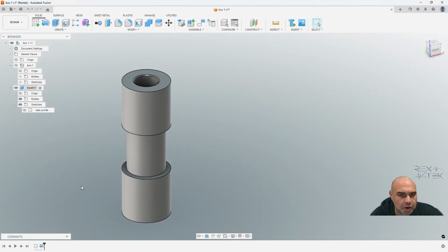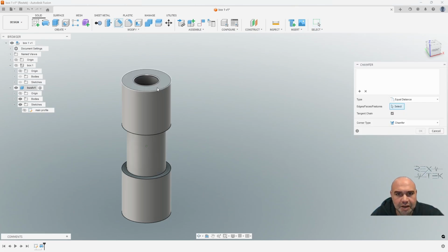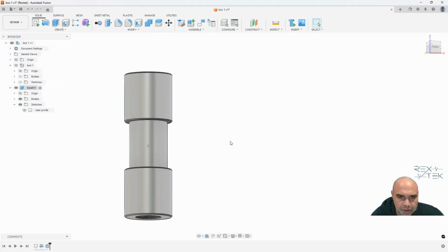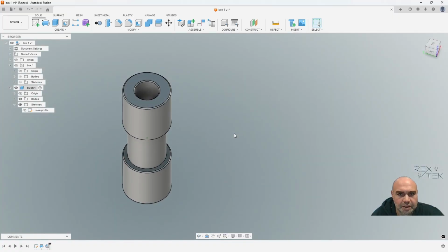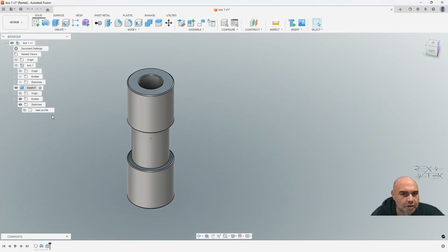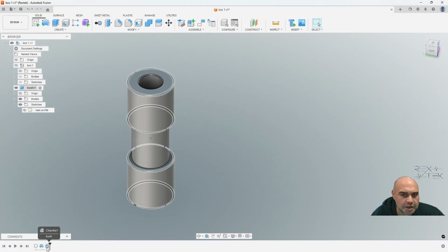A lot of the time I will do it as a solid body, so we've got our features used from our sketch here. Then we can modify the solid from this section here. So if I click chamfer there, and I do all the outside ones, 1 mil, hit enter, put 1 mil chamfer on the outside profiles, it goes down to our tree, our history, sorry.